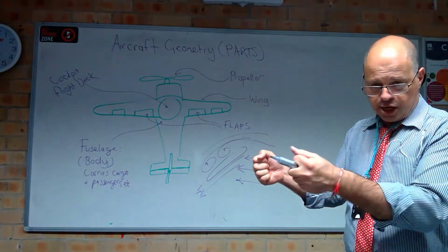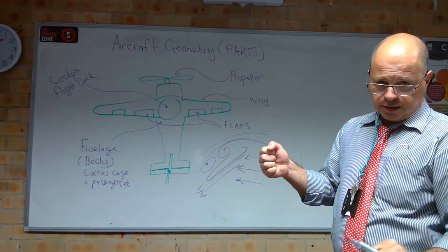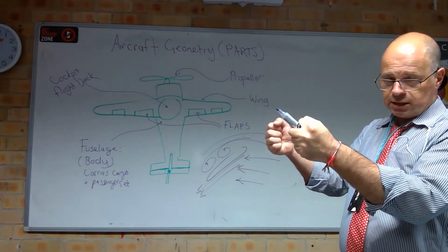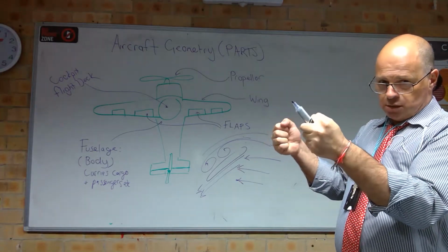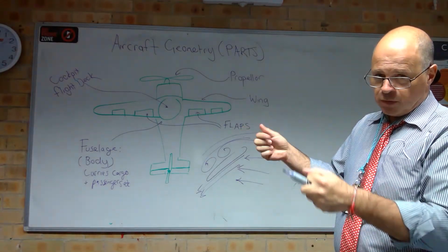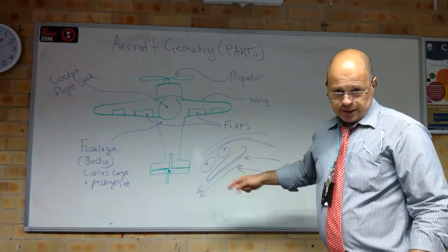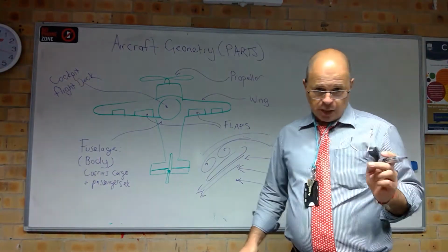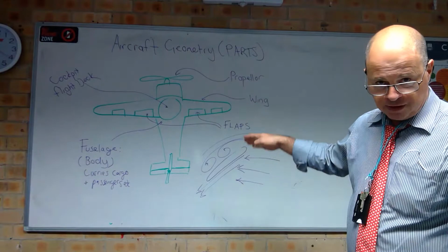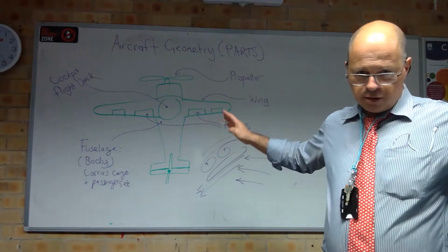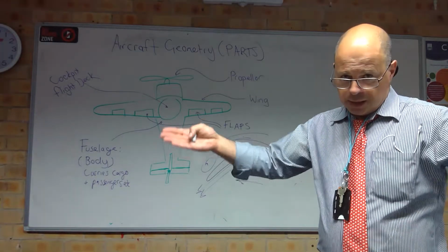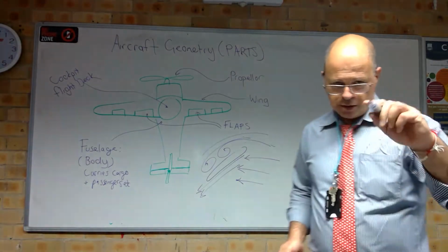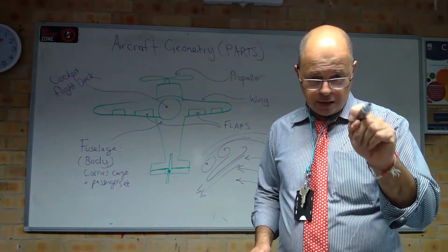So when you do your pilot training and you want to stall the aircraft, you throttle back to slow the aircraft down. You sometimes go to idle, and then you'll slowly pull back, because as the aircraft starts to slow down, if you want to maintain altitude, you can just keep pulling back and pulling back, generating more and more lift. But at some point in time, that happens and the aircraft drops. Okay, so a way of having a slower speed without stalling is by dropping the flaps. So when you reach a certain speed on approach, you can't throw the flaps out at cruising speed because it's too much wind load on the flaps as they drop. But when you get to the right speed on a light aircraft, there's normally a white arc in your airspeed indicator.